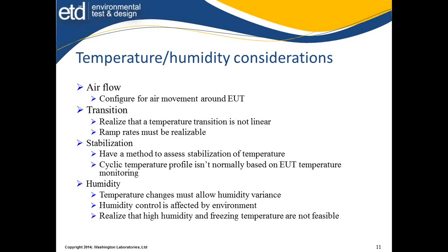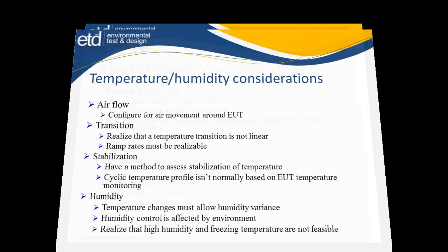Sometimes you may need to create an environment to allow your chamber to get there, chamber inside a chamber mode. It has been done before. Realize that the high humidity and freezing temperatures are not feasible. You're not going to make 95% at -8 degrees C. Not going to work. So people that believe it's going to happen, do that. Rain, salt, and immersion considerations.